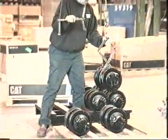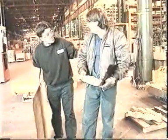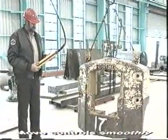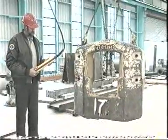When operating an overhead crane, it is important to adhere to the following safe work practices. Gently take up any slack before the load is lifted. Make sure that everyone in the immediate vicinity is clear of the load and aware that a load is being moved. Control should be moved smoothly and gradually to avoid abrupt, jerky movements which may cause the load to swing unduly.